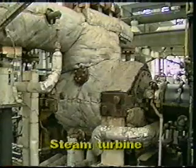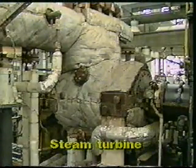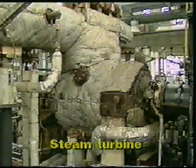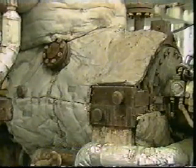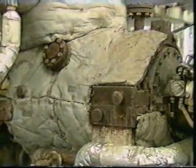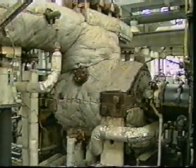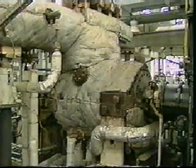In steam or combustion gas turbines, speed increasing gears are often needed between the turbines and the compressor shaft and are connected with couplings. Commonly, steam and gas turbines use speed increasing gears between the turbine and the compressor. Steam and gas turbines generally rotate at high speeds and therefore can sometimes be used to drive high-speed centrifugal compressors without any gearbox. This is known as direct drive.